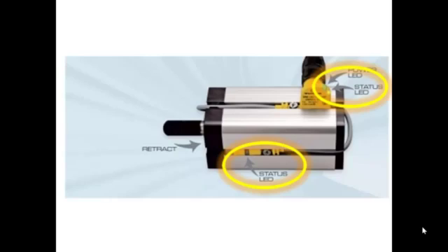Now those sensors slide in those grooves that you see them mounted in. So they're adjusted to a right position to sense the presence of the piston. Now these sensors aren't necessarily magnetic proxies. They could be inductive proxies or something called Hall sensors. Now we're not going to go off discussing the difference of these sensors, but just keep in mind these sensors have a field that is disturbed when the presence of a particular element shows up in close proximity.